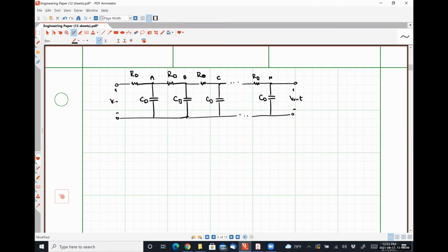Did you guys cover any transmission line theory in your 411 class with Dr. Cox? Okay. So why does it take time for signals to propagate through a transmission line? Because that's exactly what this is. Anybody got any thoughts? Why does it take time for the signal to propagate through the single RC network? Because it takes time to charge the capacitor, right? So here we have a bunch of capacitors. They're not in parallel, but we can think about it.